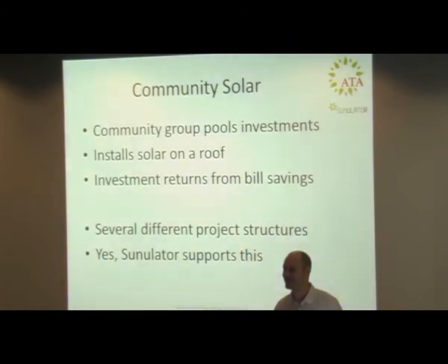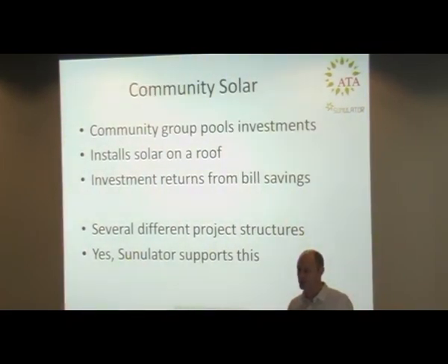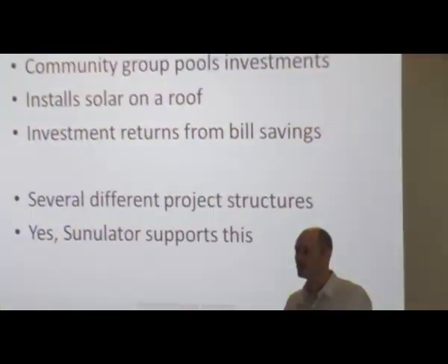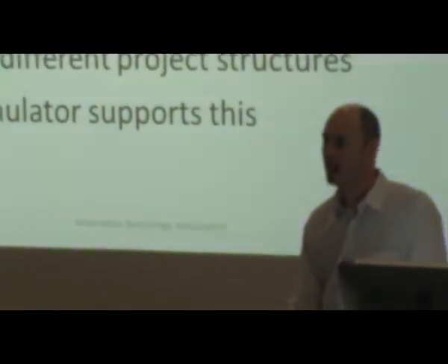What assumptions do you make for future tariffs? I think that's a pretty uncertain field. Yeah, it certainly is. Basically, the same table where you put in your panel degradation year by year, you can also put in increases or decreases in your future tariffs year by year. And it splits it out into the fixed component of the bill and the variable component per kilowatt hour. So you can put in your own assumptions. The default is just a 1% per year compounding increase into the future.